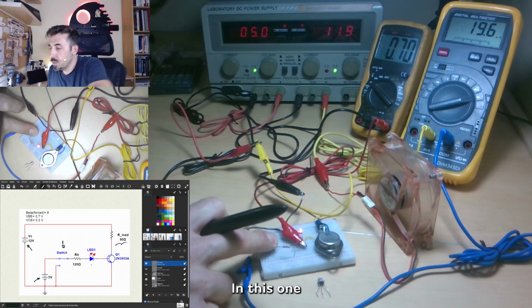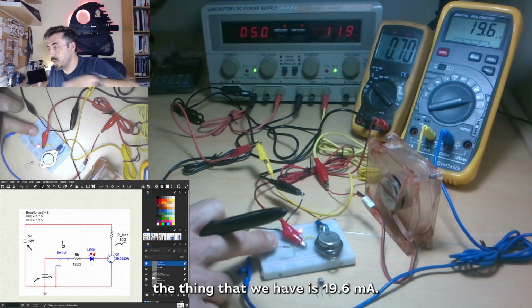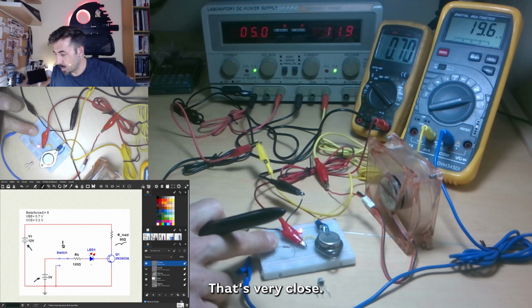So let's go for the measurement. Here we have 0.7 at the base, just the same as we computed, and for the current through the base, we have 19.6 milliamps. We computed just 19. That's very close. Everything is very close to the values that we expect.